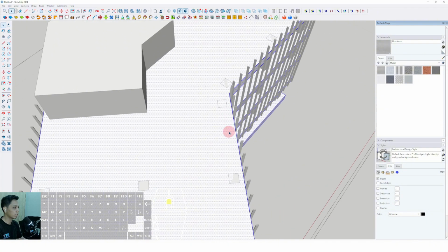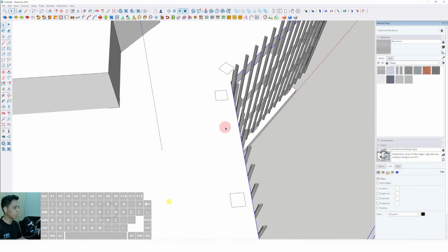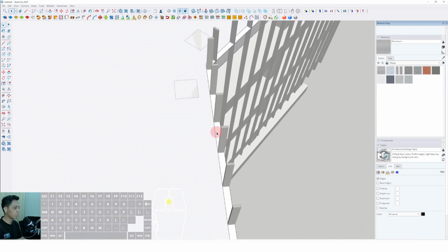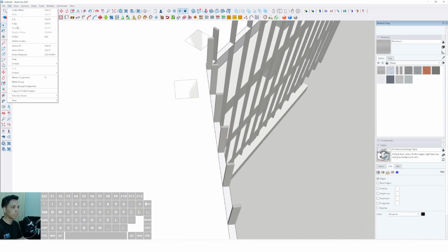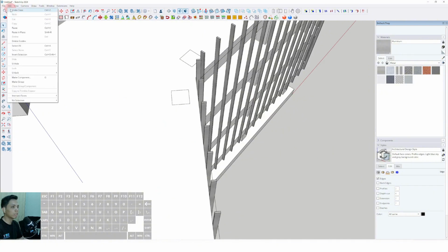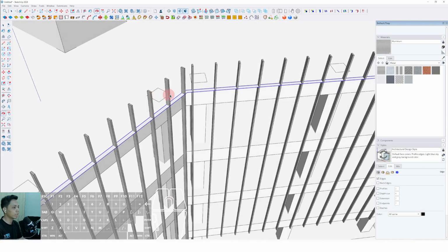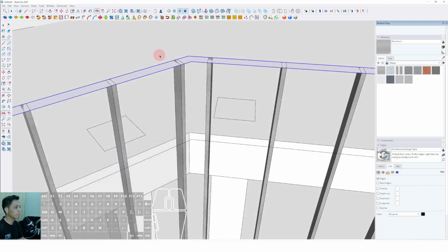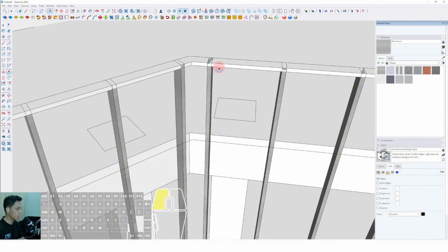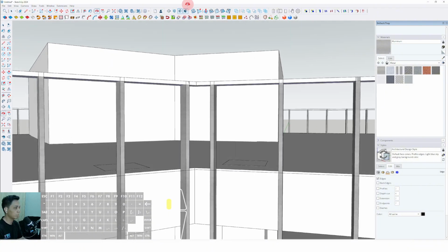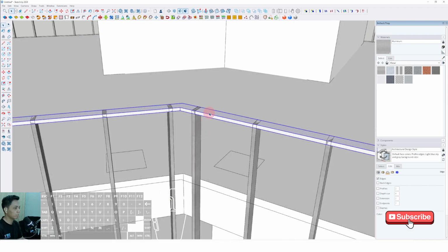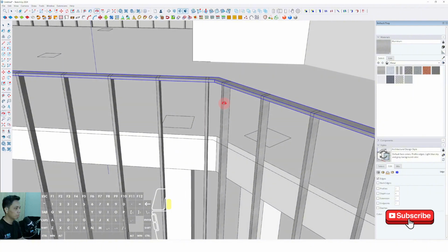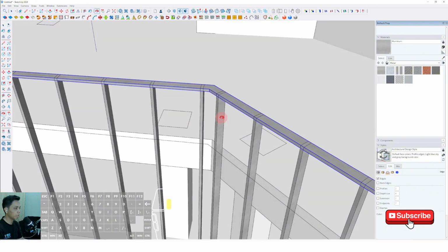We can triple click for this. We can make it unique first. We can triple click and offset it outside, place it in this position, then click this plane and edit, cut, and edit, paste in place. Then we can select move, place it to this position, then push it down around 60 millimeter approximately. Then triple click, right click and make group and click to this point.